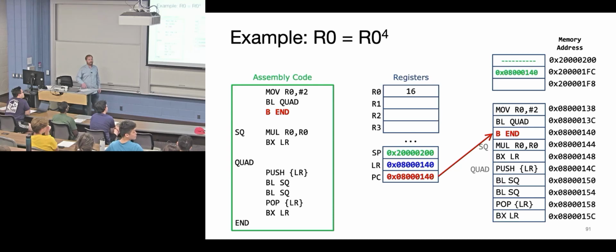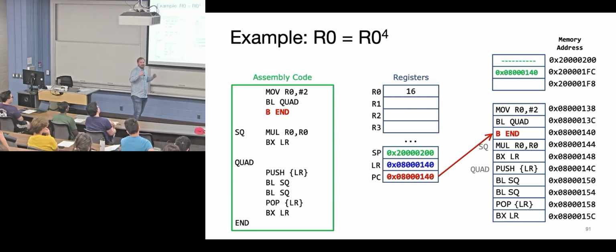So is pushing and popping register dependent, and is there some tracking on the stack of what register you pushed from? Or can I just pop into any register and push from any register? Yes, you push and pop any register you want. Okay. If you do a pop with multiple registers in it, it's going to reorder those. So if you wanted to do R7, R3, R2, R1, it's going to reorder that, but you could do pops independently if you really liked the order in which they were in the stack. If you don't care, then just use that pop function with all those variables.